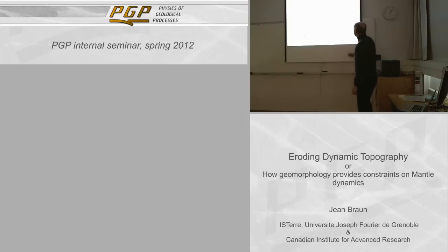And typically, when you calculate the height here, you say it's just expressing this in finite difference way, okay? It's first year applied mathematics. The new height here is the old height there, minus the finite difference expression of that term here. I've put n equals 1, okay? And that's the difference in height between these 2 points divided by the distance between the 2 points. It gives me the slope, okay? Now, this typically is something you can do explicitly, because in theory, you use the estimates of the height here and here at the previous time step. That's called, you all know that, an explicit formulation.